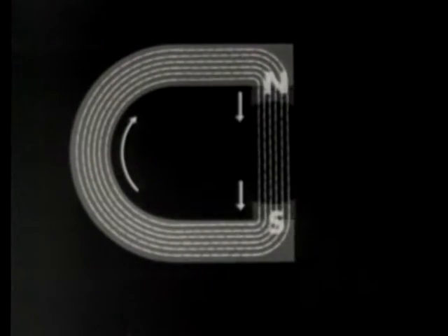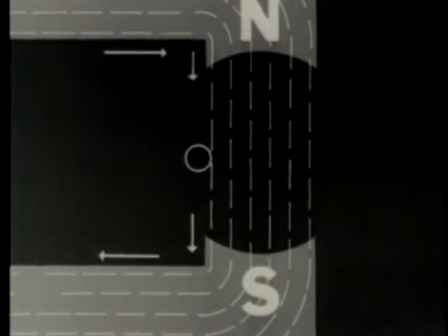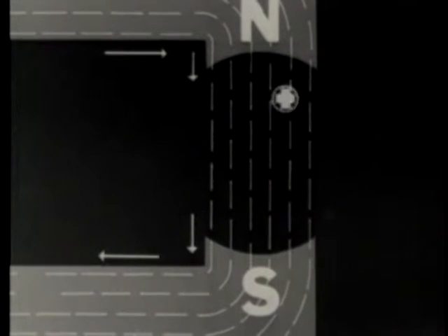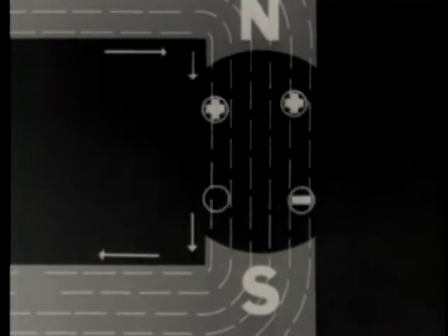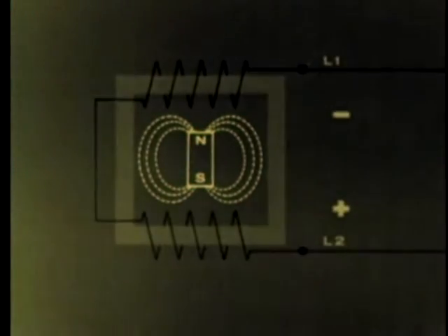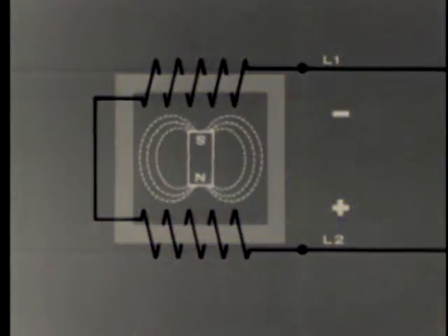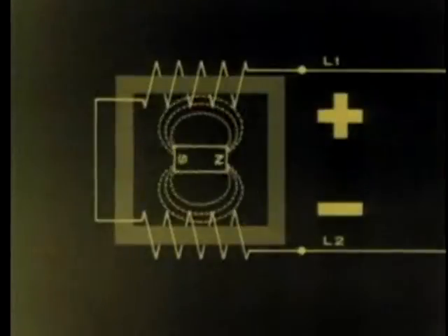If we also concentrate the magnetic field by bringing the north and south poles of a magnet closer, and either increase the speed of breaking the magnetic field or increase the number of wires rotating across the lines of force, we will have a generator. Some generator magnets are located within a coil. Each time the magnetic lines of force of the magnet rotate across the wires in the coil, a potential is induced. Because of the difference in polarity of the magnetic poles, the induced voltage is alternately negative and positive.